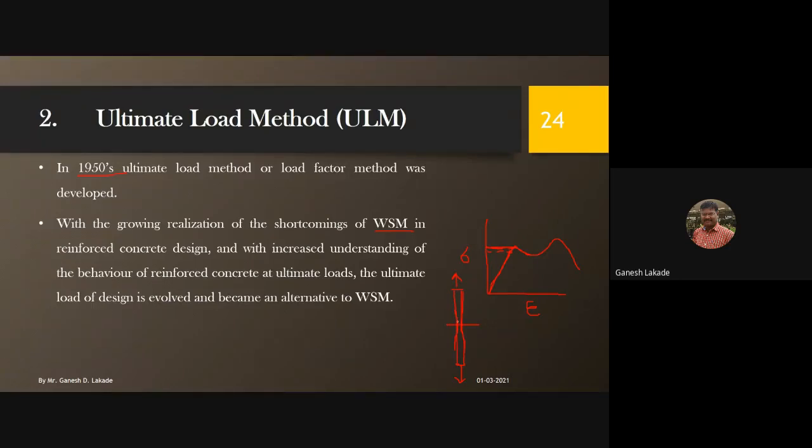As this cross-sectional area is reducing, the stress value is increasing, and after some time the steel is again going to carry the load, and after reaching the second yield point, you will find that sudden rupture of this bar will take place. So this process from this point to this point is called strain hardening, and this process is called neck formation. This necking process you have studied in the strength of materials laboratory. So this is the actual behavior of steel.